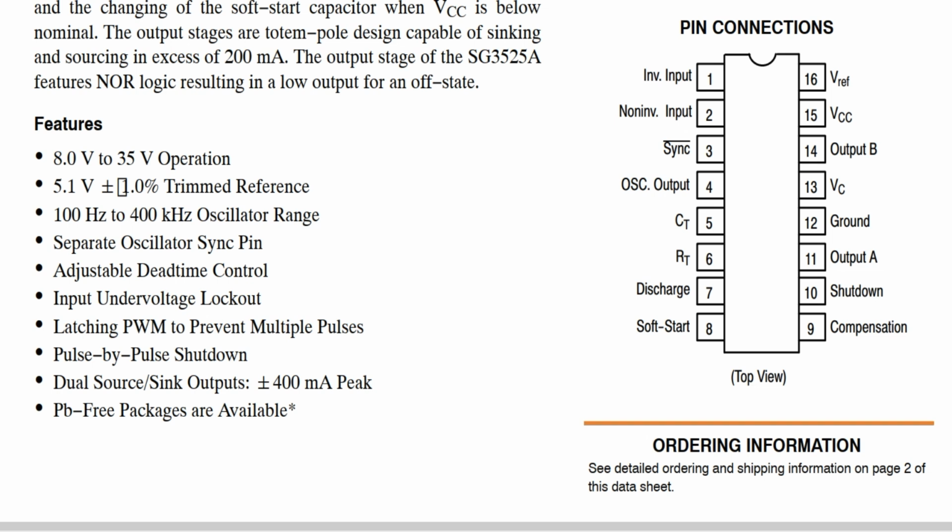Since the SG3525 itself is not available in the Proteus library, we will use a direct equivalent circuit IC in the Proteus, UC3525. This IC in the Proteus has the same function and pin configuration. The pin function of the IC is described in the datasheet.